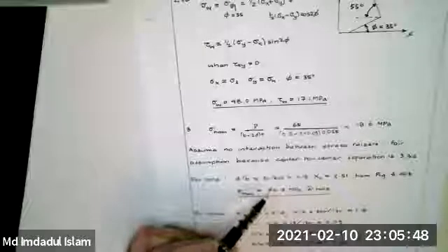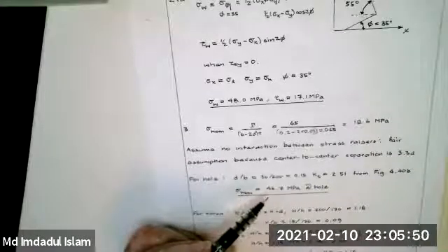Because the hole isn't there. When you say for the notch, you have h over H as 200 over 170. Why isn't it 200 over 140? Wouldn't the hole be excluded since that material's missing?